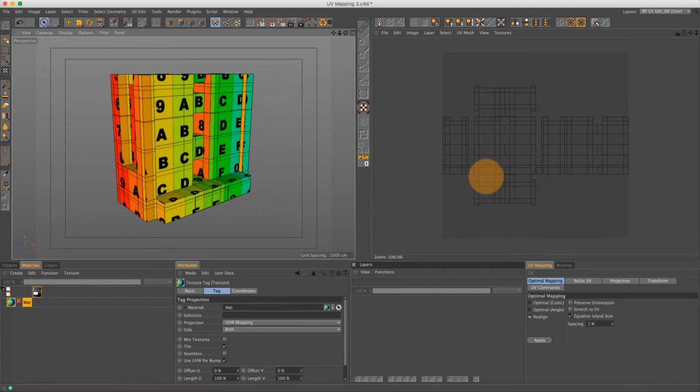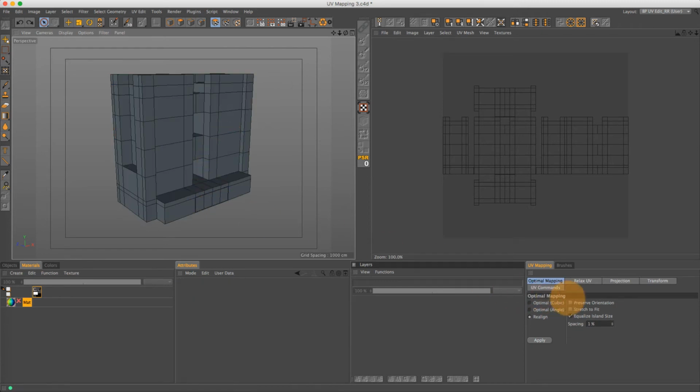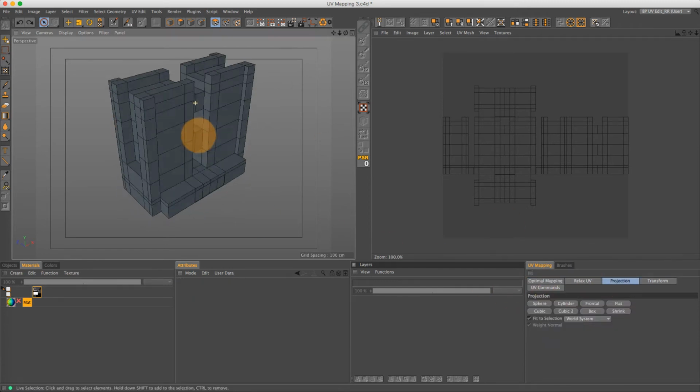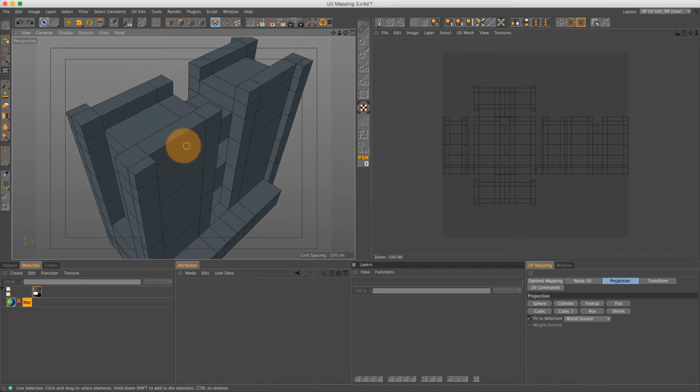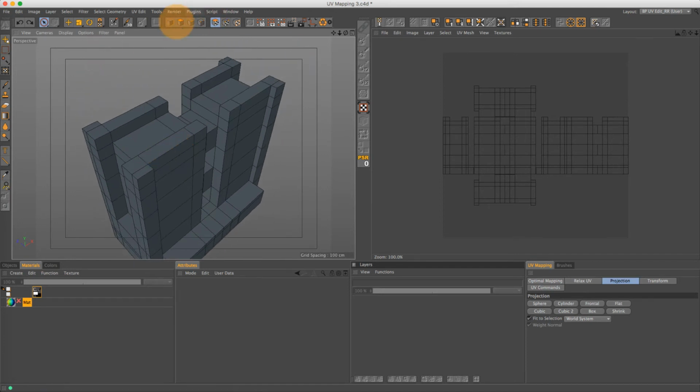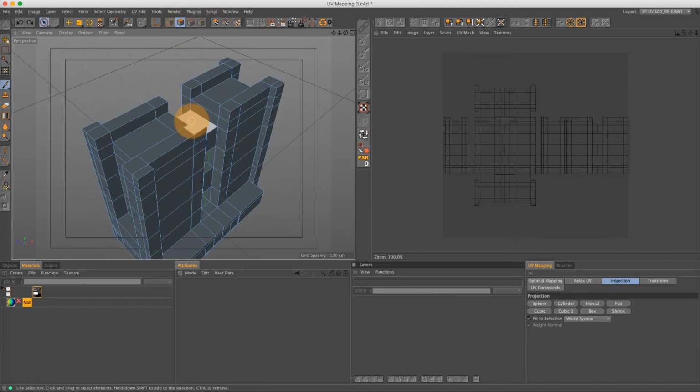But since we do have all these other UVs in this model, this option is not really beneficial to us. But we can UV unwrap this really quickly if we just kind of tell Cinema, this is the roof, this is the side of the wall, these are the things we want to connect and strip apart, and then it can go real quickly.